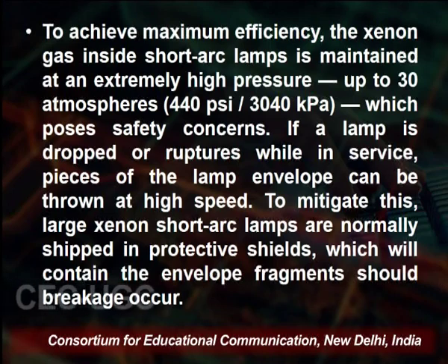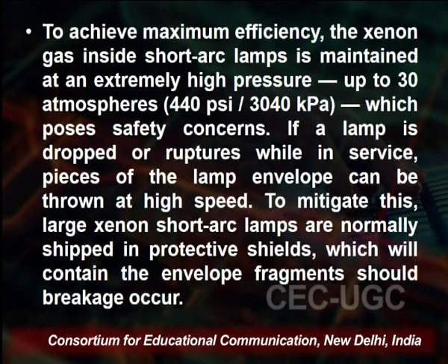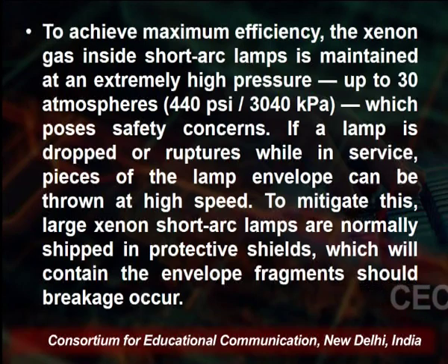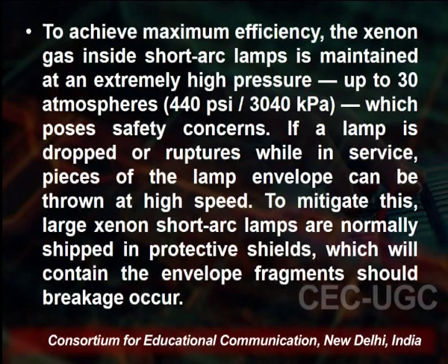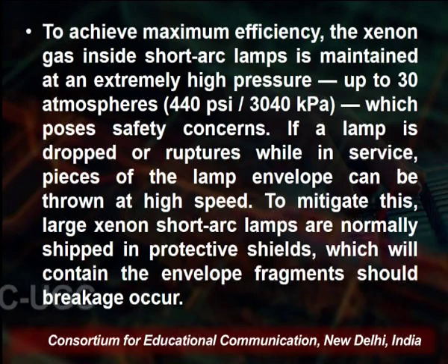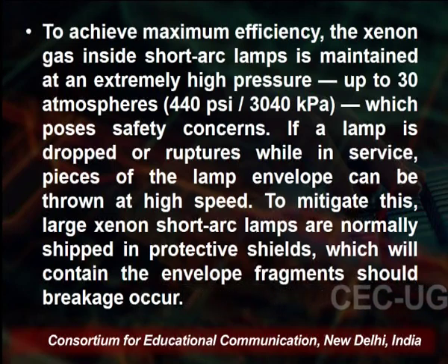The xenon inside a short arc lamp is maintained at extremely high pressure, up to 30 atmospheres, and it poses a safety concern if the lamp is dropped or broken while in service. The pieces of the lamp envelope can be thrown at high speed.